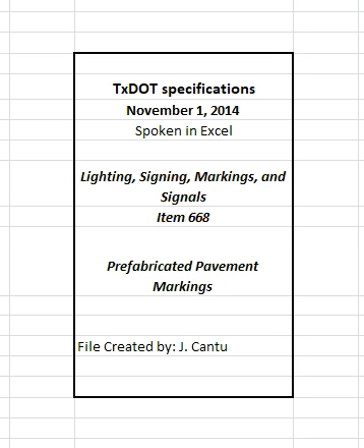3.2.2 Temperature. Follow pavement and ambient air temperature requirements recommended by the material manufacturer. Do not place material when the pavement temperature is below 60 degrees Fahrenheit or above 120 degrees Fahrenheit if the material manufacturer does not establish temperature requirements.